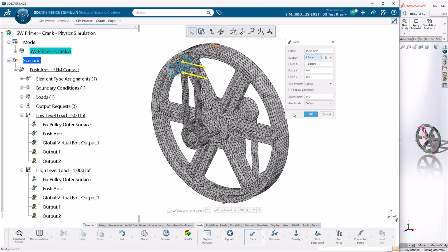We could also then specify an amplitude curve. This is the same concept as the time history curve in SOLIDWORKS, so that the load will change as the step progresses. These amplitude curves are defined in the Setup tab and then selected in the feature as needed. Note, in addition to directly using coordinate systems, the floating toolbar also provides alternate ways to define the load direction. Here we will continue to use the global coordinate system as it is convenient for this analysis.